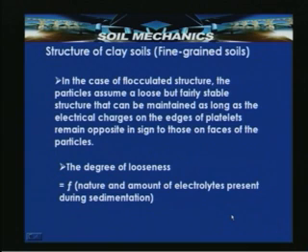In the case of a flocculated structure, the particles assume a loose but fairly stable structure that can be maintained as long as the electrical charges on the edges of the platelets remain opposite in sign to those on the faces of the particles. The degree of looseness of a flocculated arrangement is a function of the nature and amount of electrolytes present during sedimentation.